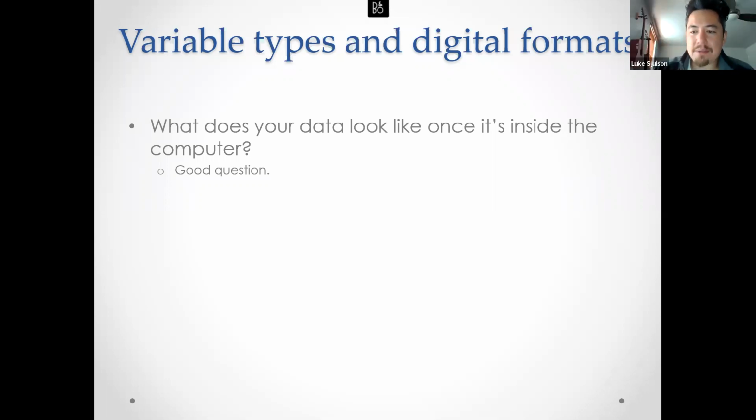The reason people often have to do high pass filtering with stuff like electrophysiology is more a question of dynamic range. Let's talk about that in the electrophysiology lecture. But there's no physiological signal above 8 kilohertz, though there is noise above 8 kilohertz. If you just have an electrode, thermal vibrations and whatever create noise at these higher frequencies. If you're not low pass filtering, you're sampling all that noise, and that high frequency noise gets aliased down into the frequency ranges of the signals you're trying to record.